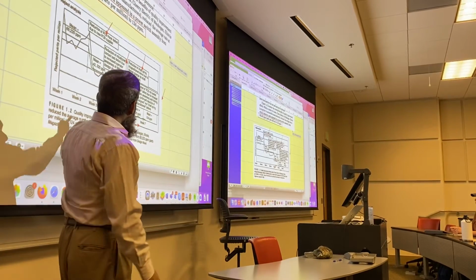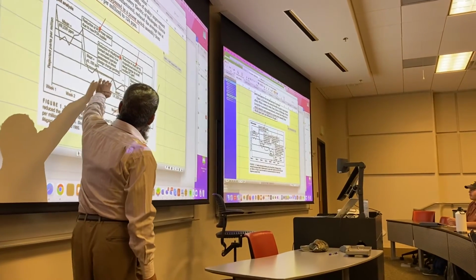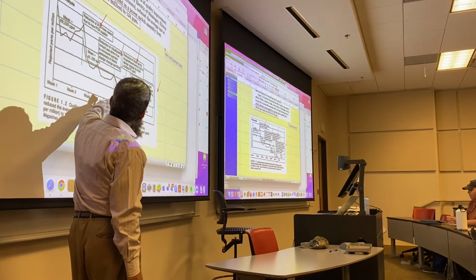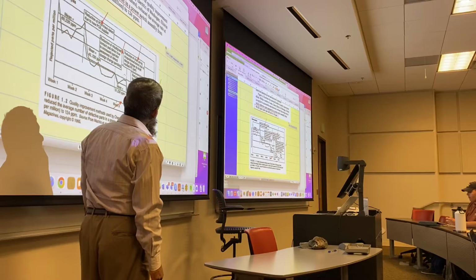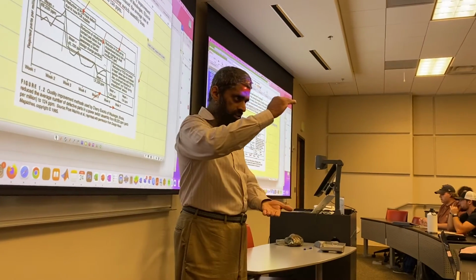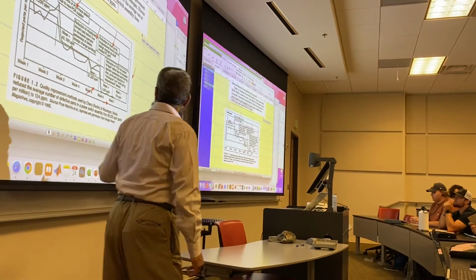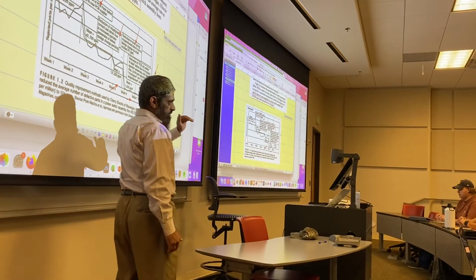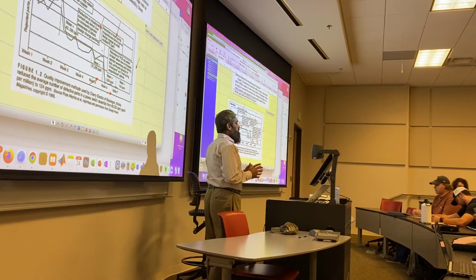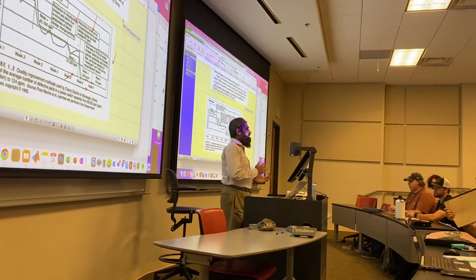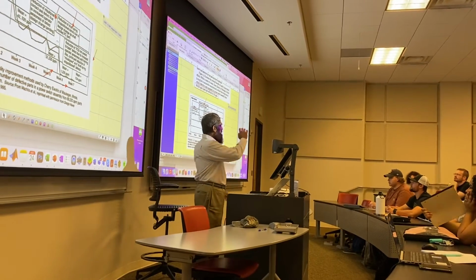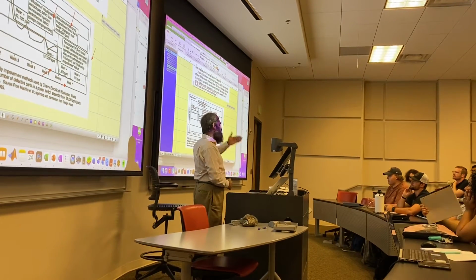The third change they made was the reduction of the misaligned contact pad defect due to increased operator awareness. By teaching the machinist that if you follow a method like a checklist, you can reduce the number of defects. So we have to keep in mind that the machinist should also be knowledgeable about what he is doing. It is good practice that in a machine shop you put up a chart, a poster with the checklist.